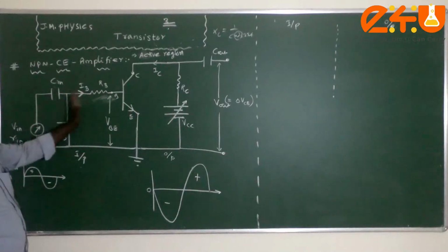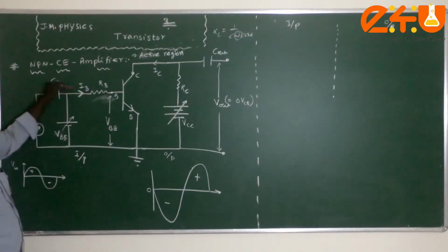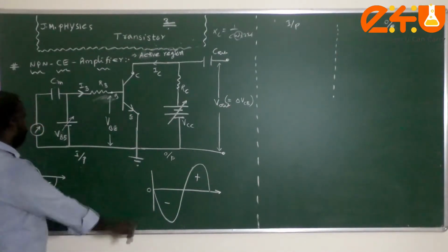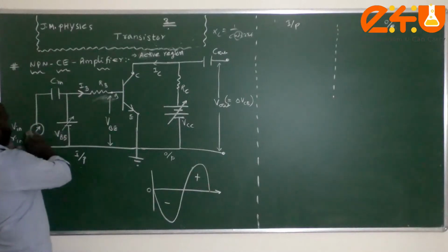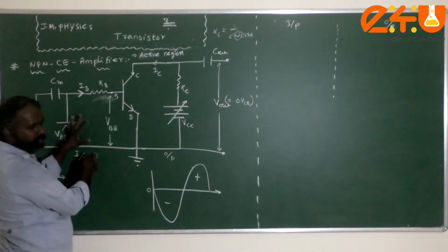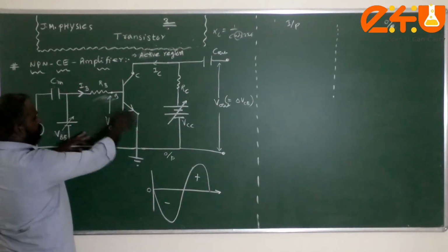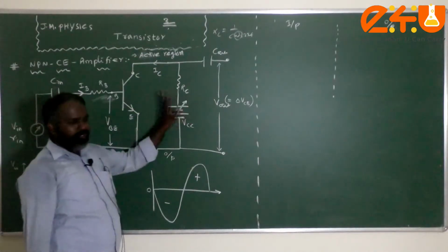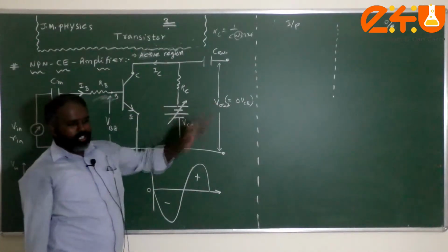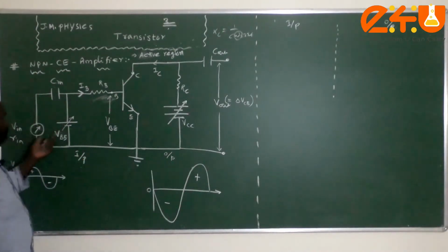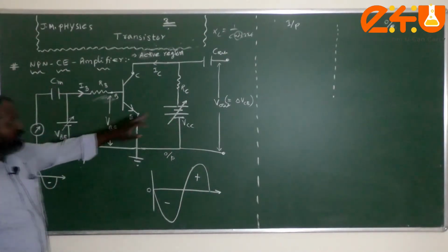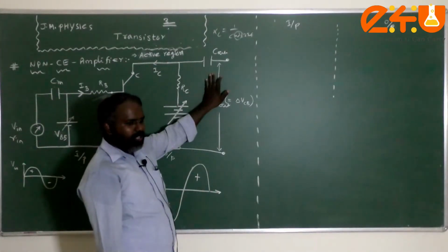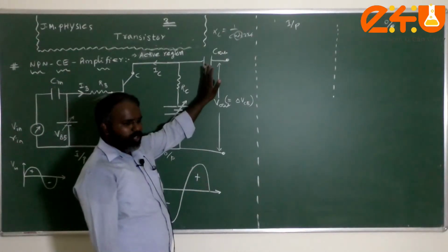So when it crosses this point, it contains only the pure sinusoidal signal, the signal in the sense of voltage. Okay. What will happen when the voltage changes? There will be a corresponding change in the input, what is that? Voltage biasing the transistor, and whatever change happens in the input part will be reflected in the output part. That explanation we are going to give, but I am just telling what will happen, why the input capacitance and output capacitance are used. Similarly, at the output capacitance, if the signal contains any DC component, that will be completely stopped by this output capacitance only.